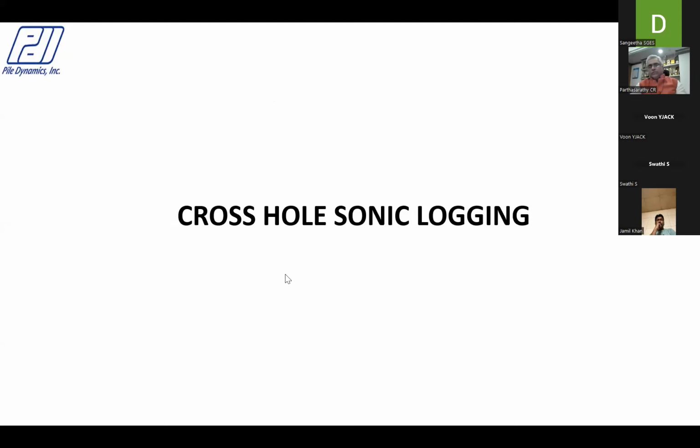So now we discussed about the squid, we discussed about the shape, which is prior to pouring the concrete. Then we discussed about the bidirectional load test, a glimpse of high strain dynamic test, the instrumenting strain and accelerometers below the pile top and getting a force velocity time history, bringing the data set into the CAPWAP to perform a CAPWAP analysis to get the total capacity and the distribution of capacity between skin and the base. Now let us examine other two integrity methods.